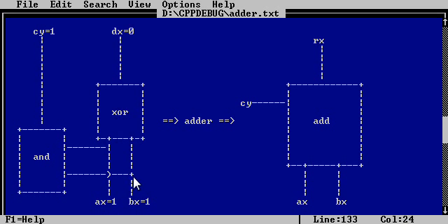These are connected. These two, AX and BX, we can go find cases. If they're both 0, XOR is 0, and these are connected to here. Again, this is going underneath here, and it's not touching the wires. These are going into an AND, but they're both 0, and so this would actually be 0 in that case.